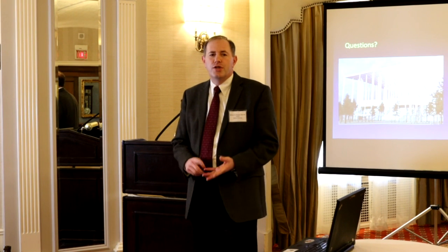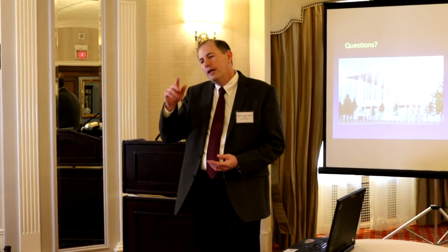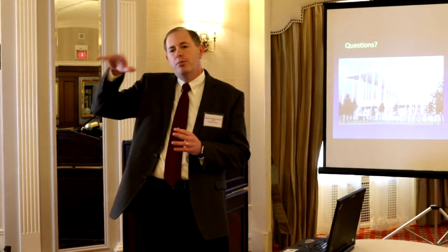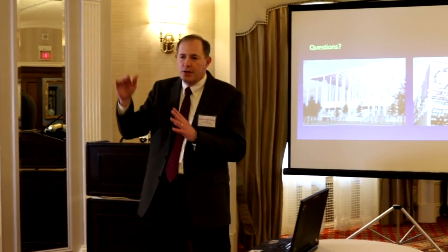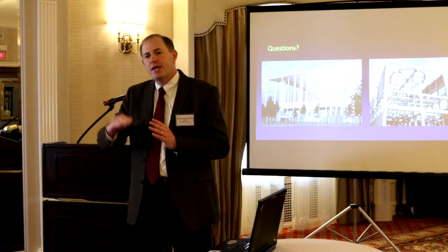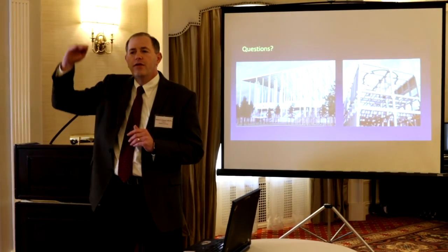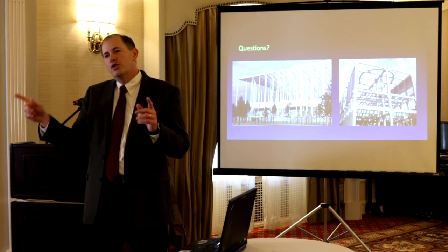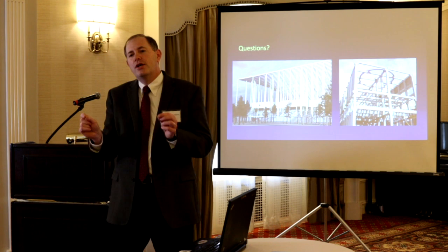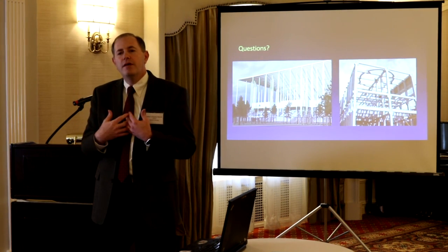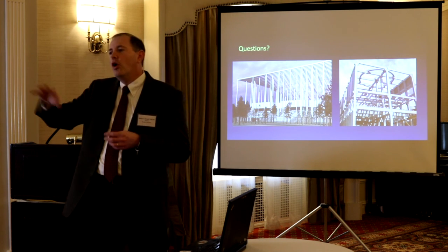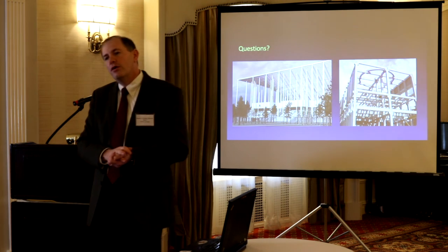Yes, we definitely need more research on the sustained load effect. What I would like to do is take the same column and sustain it at different loads. We were trying to push the columns, look at the 1.4. I'd like to take the same column and sustain it at 10, 30, 40, different sustained loads, because I believe that will show us how much sustained load matters. The lower my load level, obviously not as much is happening. I believe it will show the 1.0 is going to work beautifully, and that we can predict them all the way up essentially to final failure.